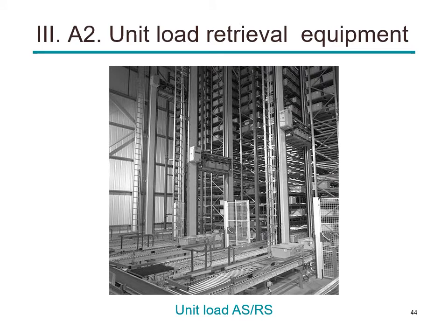And this is an example of a unit load ASRS system. You see in this ASRS system, it's an automated storage and retrieval system, and you see the racks are very high and the aisles very narrow, and these automated storage devices are assigned to each aisle. So this ASRS device cannot go out from this aisle and enter into this one. At each aisle there is a certain device that's operating. They are very fast, they are automated, and they are instructed by the computer. And no human operators are allowed inside these systems because it's dangerous.